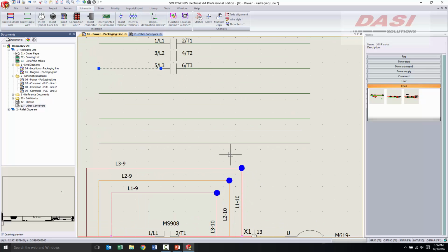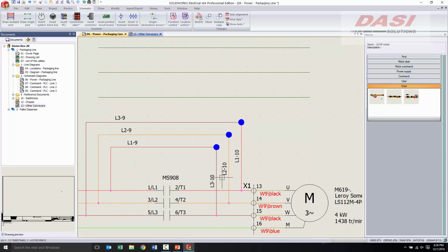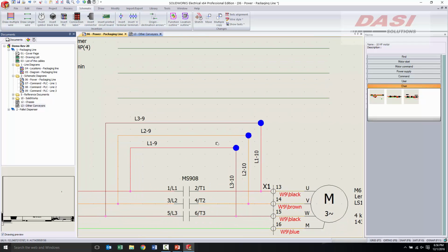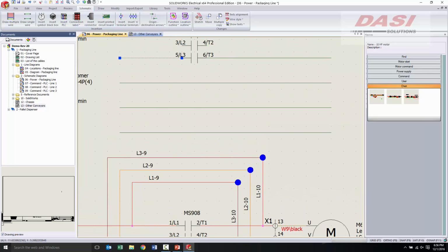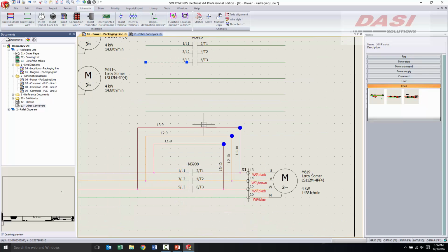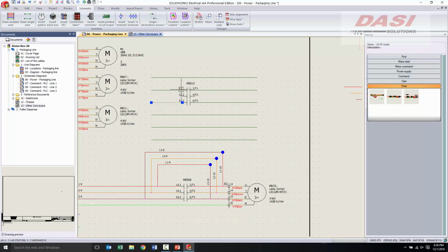I pulled that circuit from here. Notice the blue dots. You got mad, well, notice why. This is L310. This is L19. Different wire designation all the way across the board because this was a reversing motor starter. So it knows that there is a problem here now with those 3 wires. And it tells you.